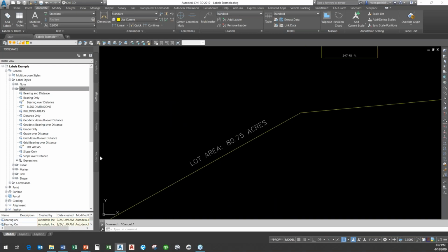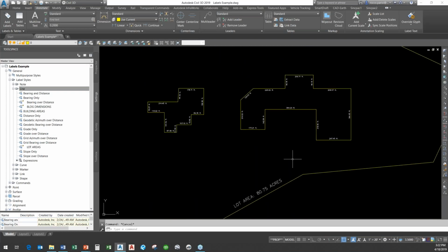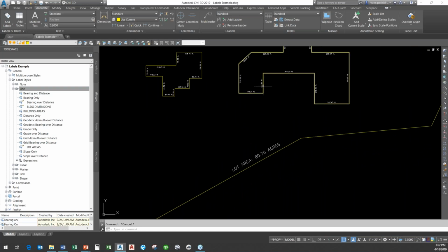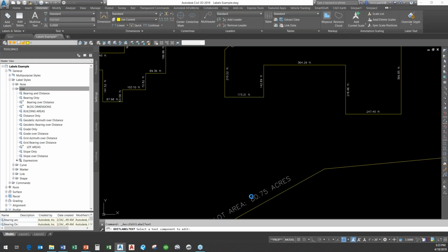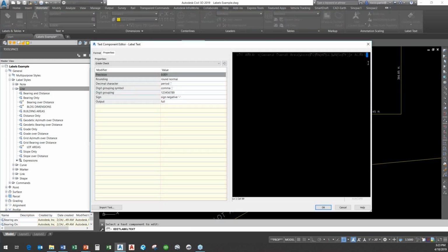All right, I got another question from Terrence. It says, can I add text like building numbers to style or individual buildings? Yeah, absolutely. Like I was showing you, you can go in any of these, same thing. It does not matter whether it's in the acreage or whatever, you can go on any text label and just hit the edit label text and pick that item. And you can go in and either before or after type building numbers or anything that you want.